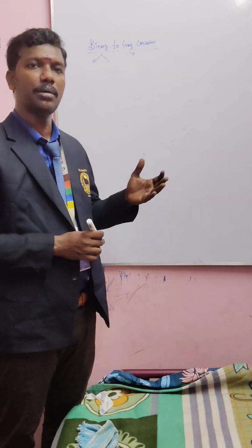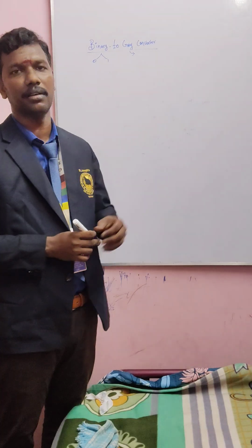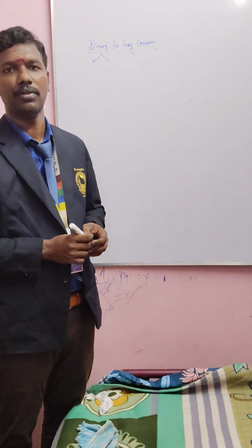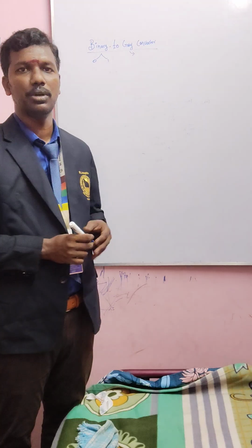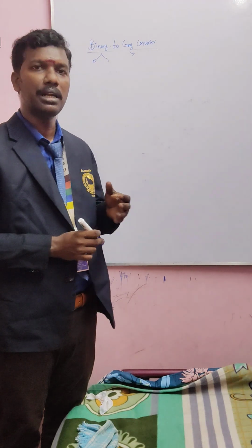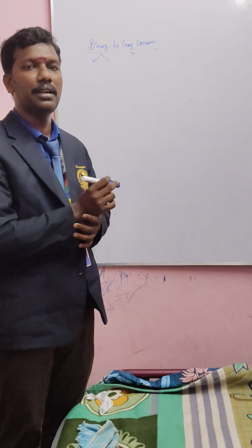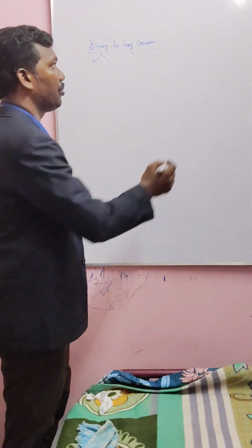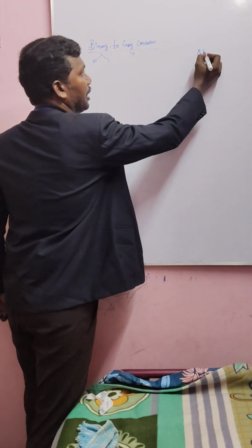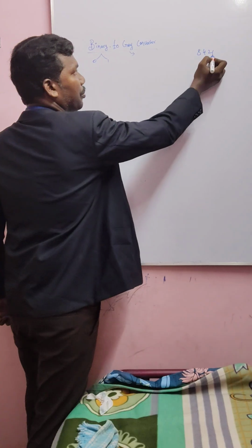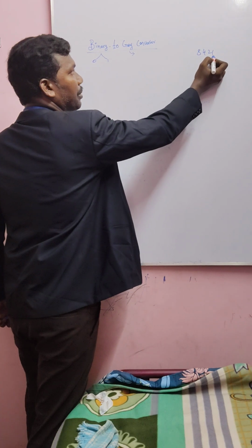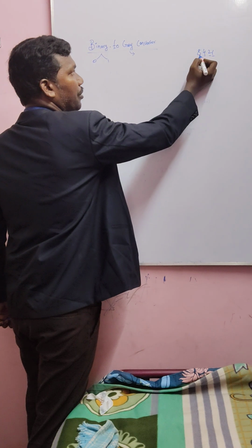So we have different types of weighted code. That means positionally weighted is called a weighted code. In that, 8421, 2421, 5421, multiple things are there, right? Basically, we are taking 8421. This is a code we usually represent. 8421 means that this is positionally weighted. The first bit position will be 1 and this will be 2 and this will be 4 and 8.